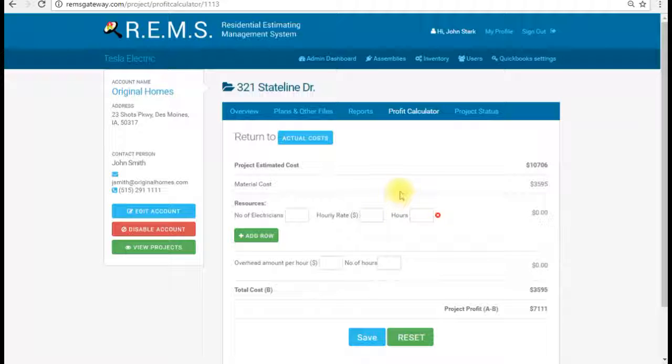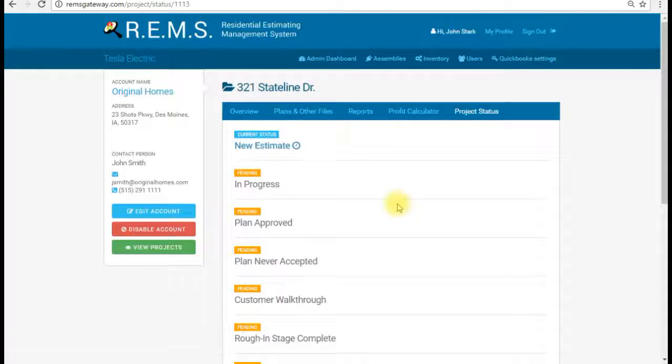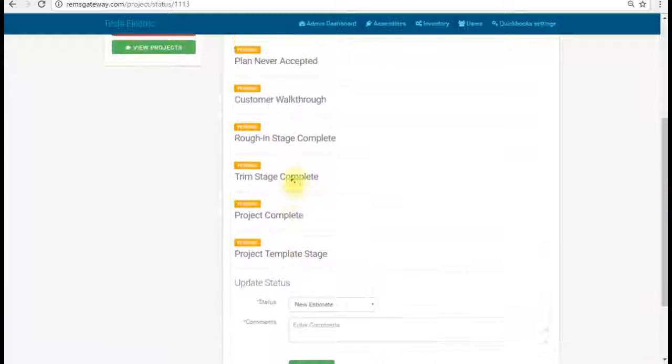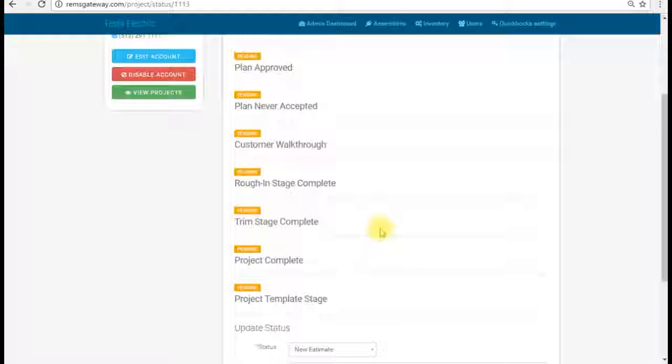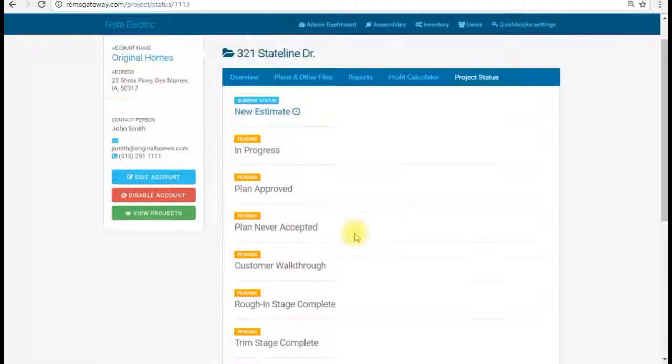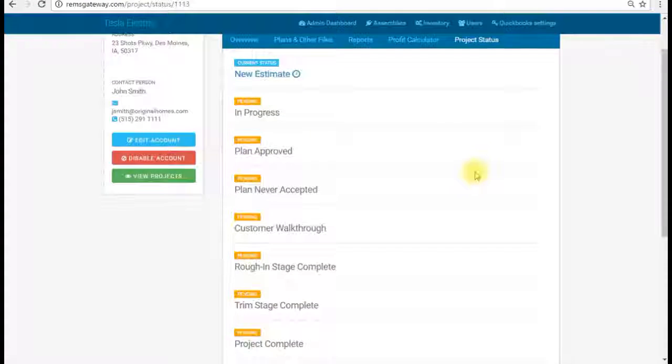And these plans also, same thing. They can be changed to a template. So we can go down and change this plan to a template for future plans. It would just include all those takeoff items in transparent in the takeoff, and we can use that for other plans in the future. So that is how you use transparent mode. It's a pretty slick feature. It's a very nice takeoff option that allows you to really get a good accurate count.